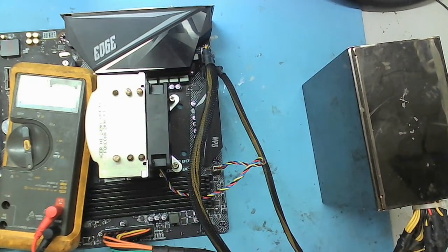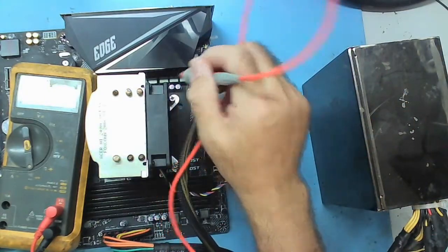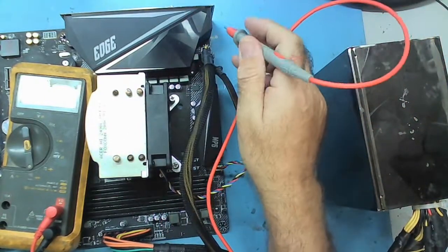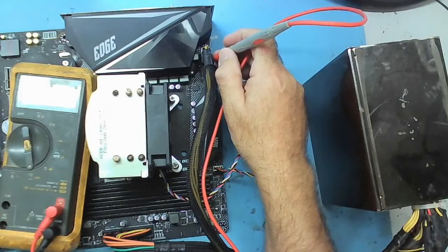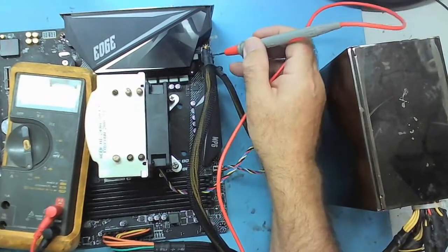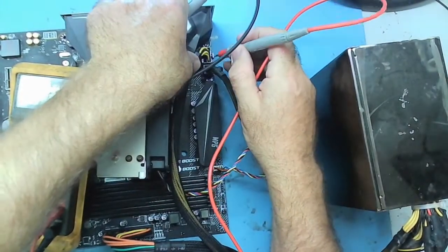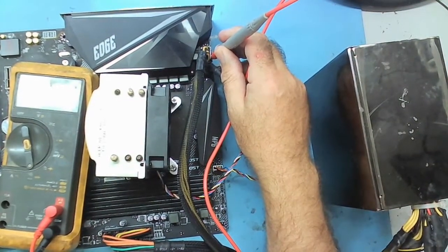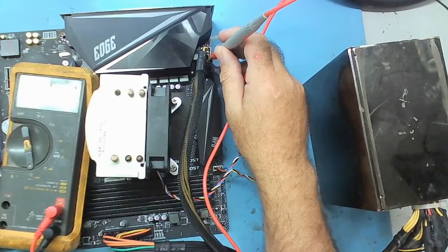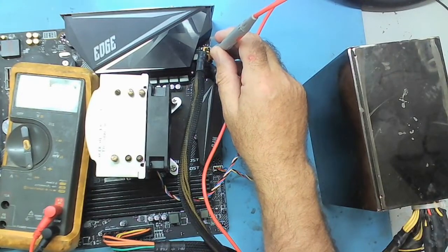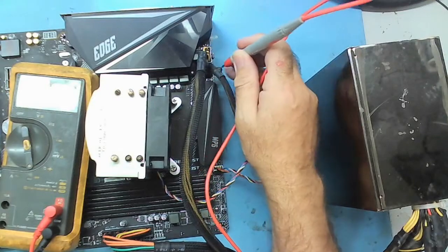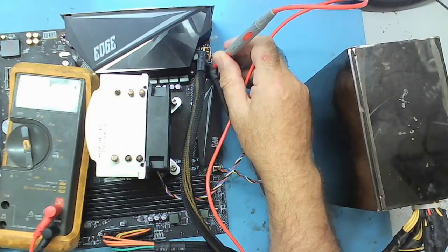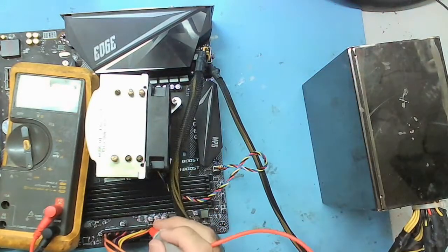That's the thing. If you've got short circuit high side MOSFETs in the VRM, your CPU is now most likely toast. So from the yellow here, all the yellows should be connected together. So just from any of the yellows, we're on ohms range, and we'll go to ground somewhere on the thing. No, we don't have a short. That's good. That's a good sign. Just check from the other one. No, we don't have a short. That's good. No shorts on there.